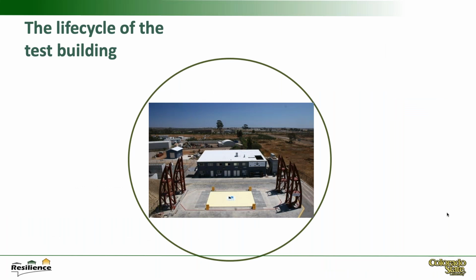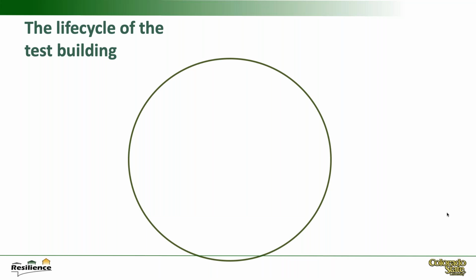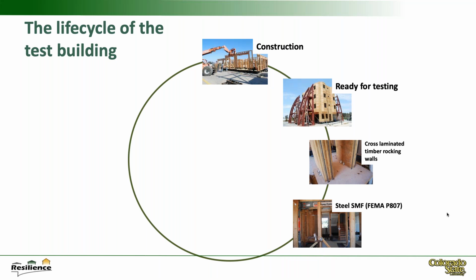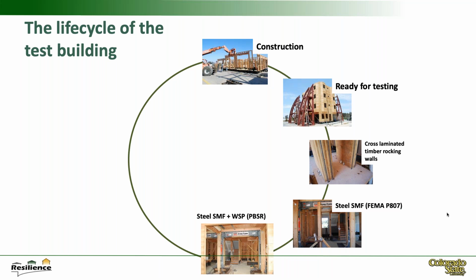So going to the world's largest outdoor shake table, or largest shake table in the US, located at UC San Diego. So we developed a building, or constructed a building, back in 2013. You can see it's ready for testing. I'll go into this a little more, but we had some cross-laminated timber rocking wall retrofit. And so each of these was on the order of about 7 to 10 days to run the experiment, and then pull the retrofit out and replace and conduct repairs, as well as the steel special moment frame.